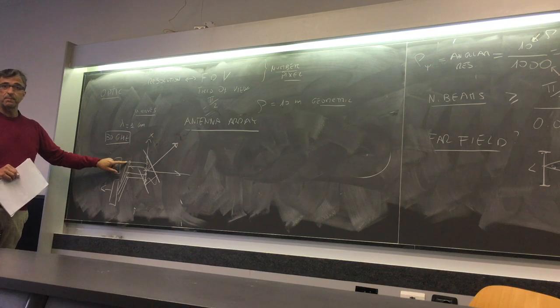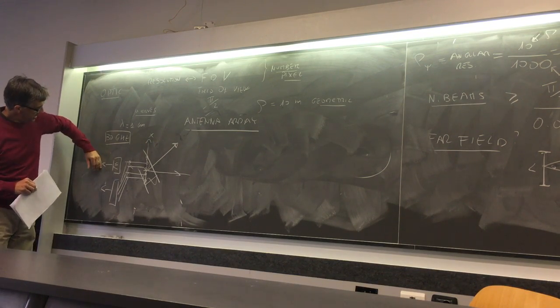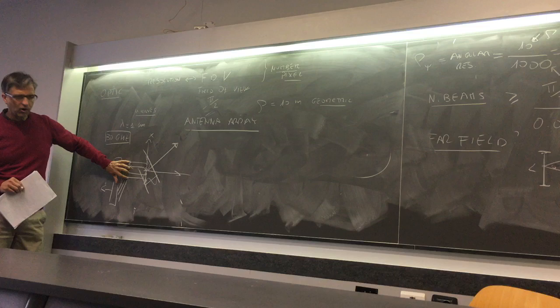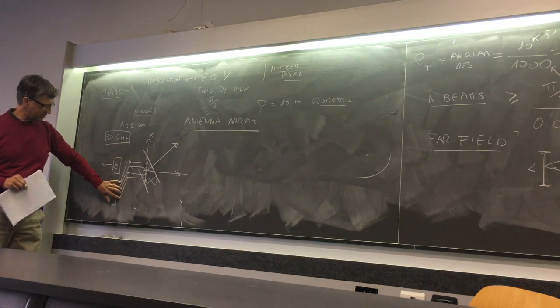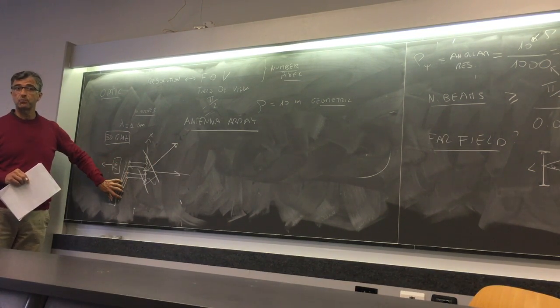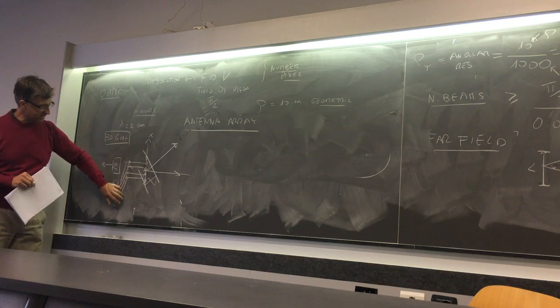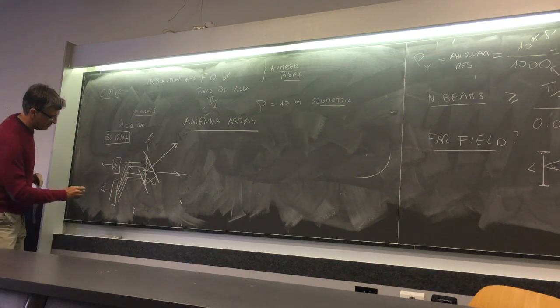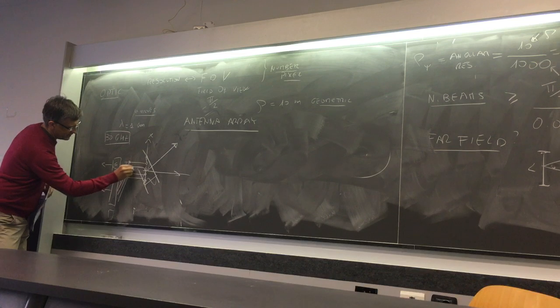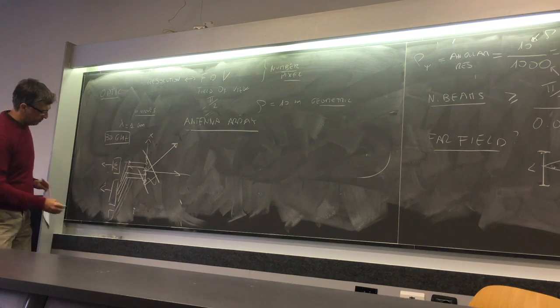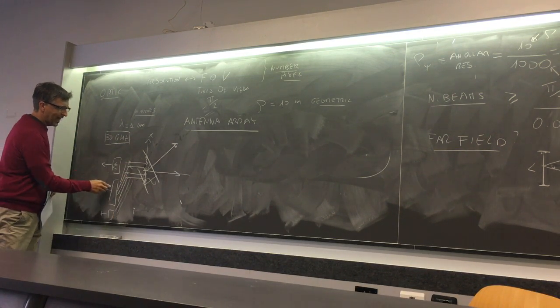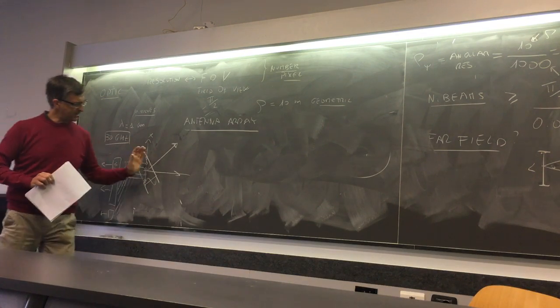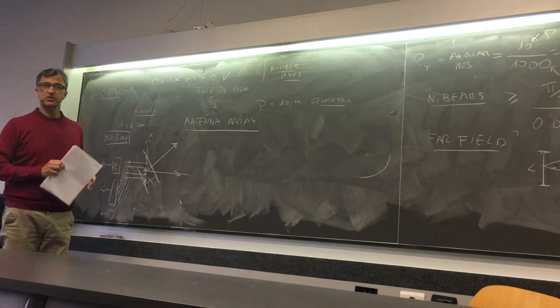The point is that steering the beam here is just a combination, and steering the beam in another direction is another combination. So you can feed the same signal received by the same antenna to different combiners, properly combined, and simultaneously you have the gain in this direction, and so on.